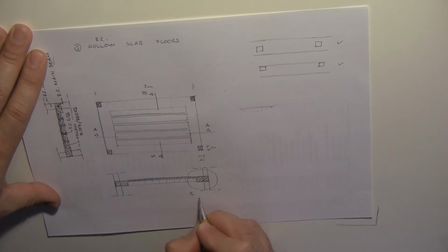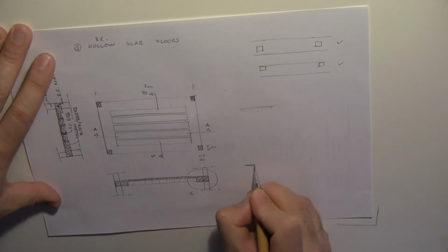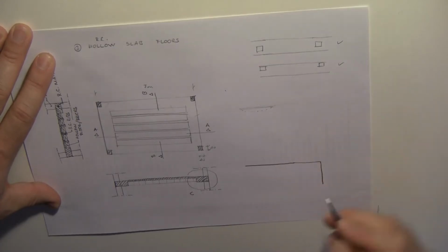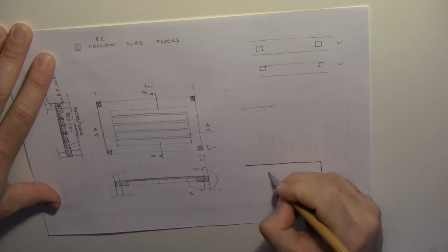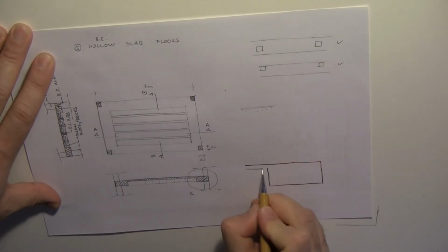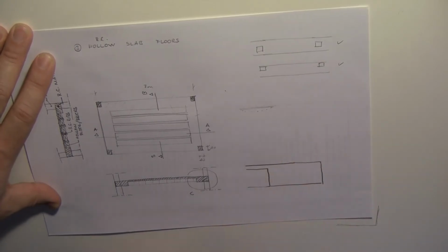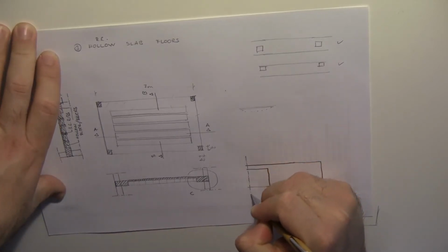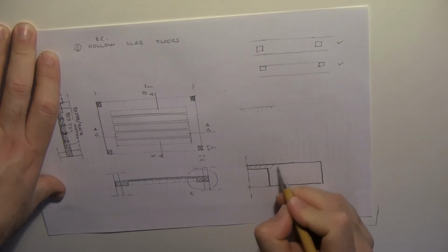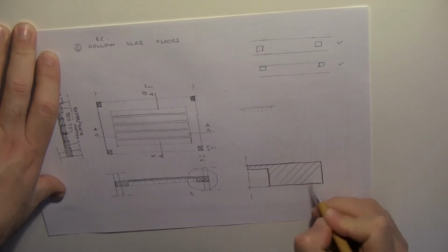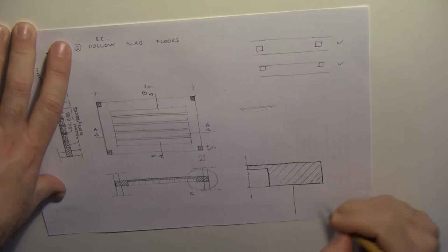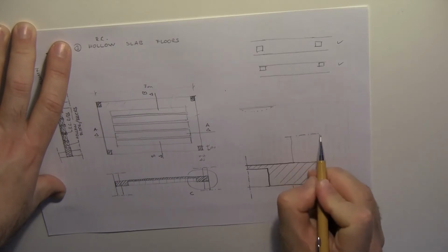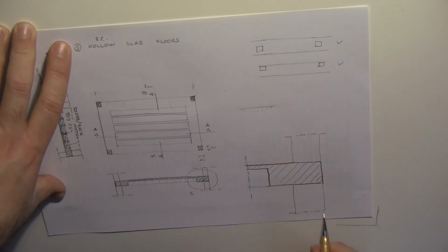Okay, let's say that it's a C. The C detail will be something like, okay, let's extend it some more. This is my main beam. Okay, this is the beam, and a fainter line here which is representing the hollow brick row. Okay, and I will hatch here in order to represent that it is entirely reinforced concrete, and here is my column in the background. Okay, and dashed and dotted line here, and dashed and dotted line here as well.